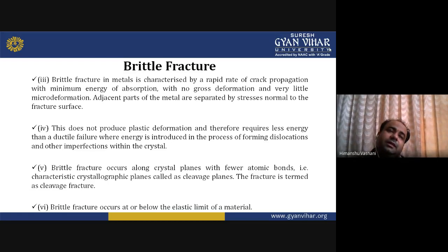Okay, because in ductile fracture the elongation will happen, so energy absorption is there. In brittle fracture, the fracture occurs along crystal planes with fewer atomic bonds, characteristic crystallographic planes called cleavage planes. So the fracture is termed cleavage fracture, very easy to understand.